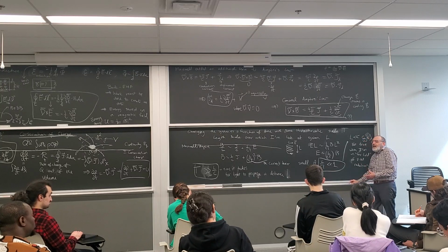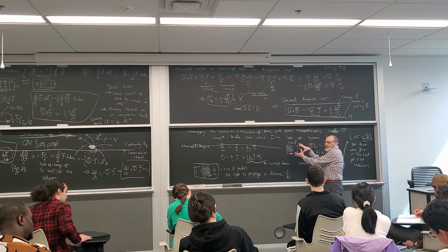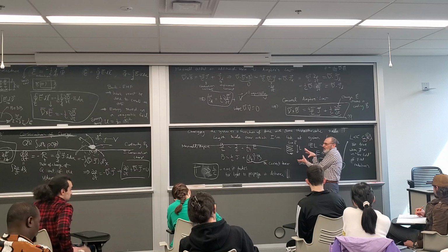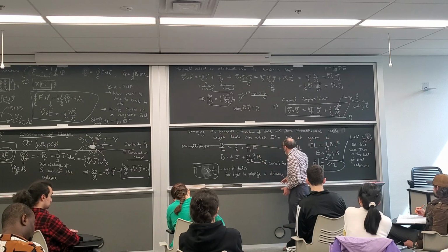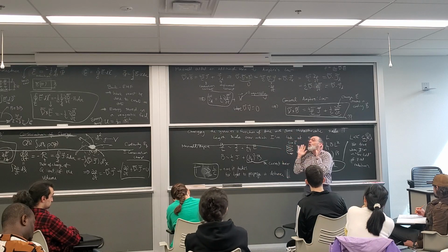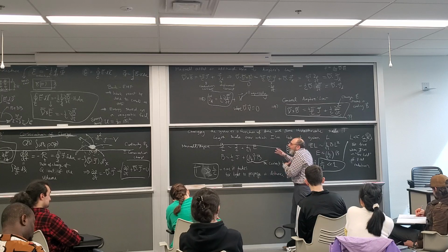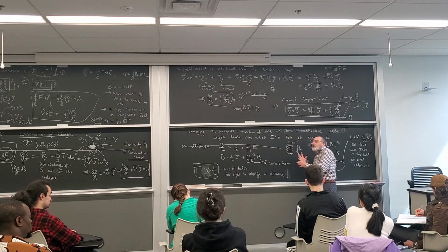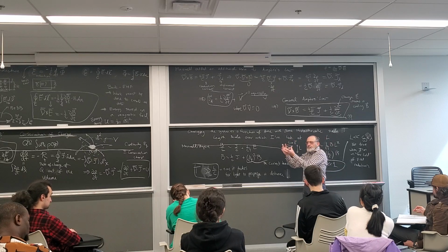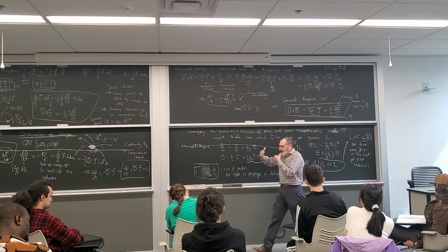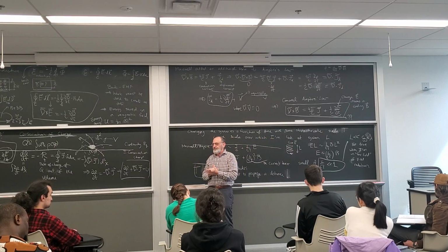So this is saying if I'm close compared to the wavelength of the radiation, I'm in the near field, and in that case, I can ignore the displacement current, and we call that quasi-static. Even though it's not static, I treat it like statics because it's just as if it were the instantaneous value of the current, because the retardation effects having to do with a finite propagation time are negligible.